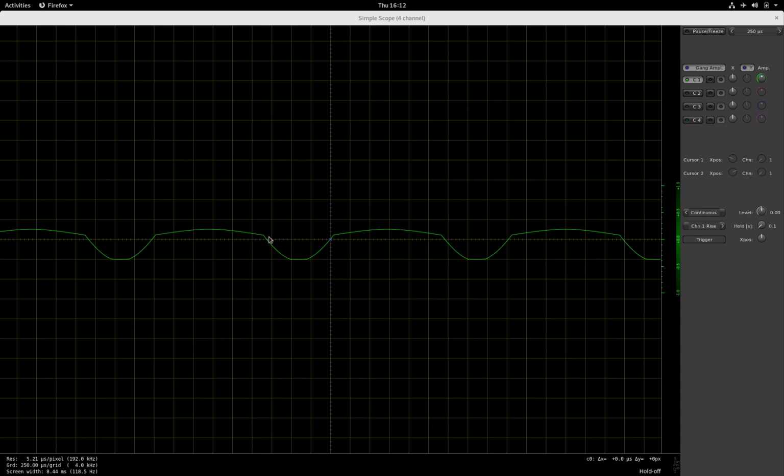And of course, the change in voltage that occurs across this nonlinear region is now lower, because the amount of gain that the fuzz applies, even though it's pretty large, is still finite. So you will see a lower slope of the signal, or a slower change in voltage here.